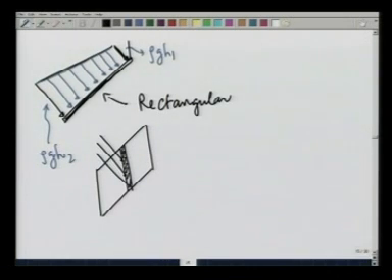This is how the pressure is working. If this were not rectangular, the force at different points would vary according to how the area changes. So, now the force depends only on the depth, because the area for each strip is a constant. So, then loading becomes linear. So, now we are being restrictive to rectangular sheets.